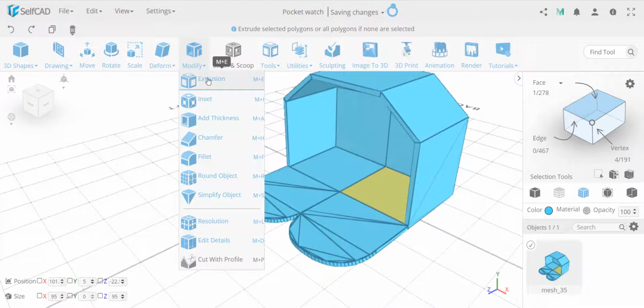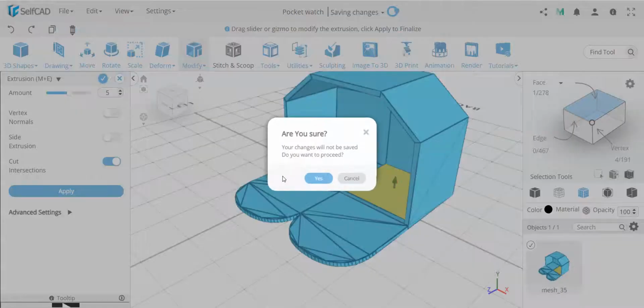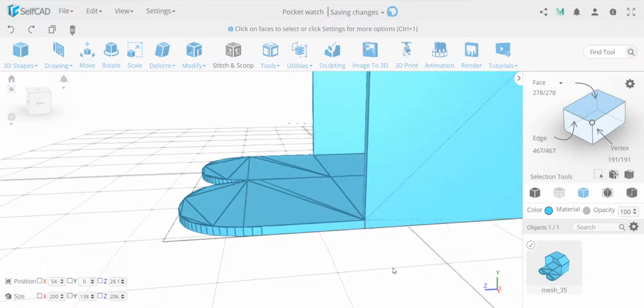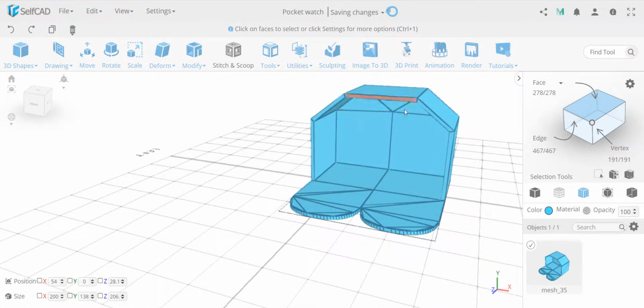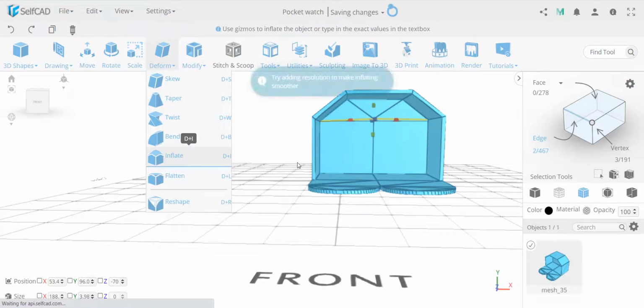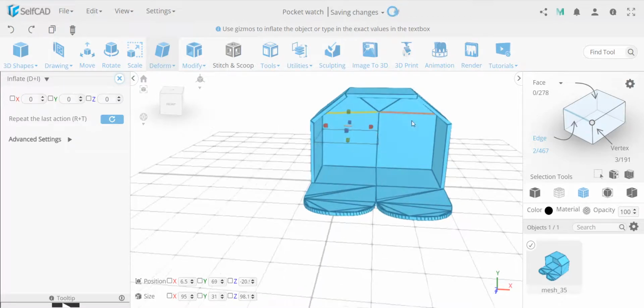You see the message is no longer showing that it's not manifold, because the object is now perfectly manifold because the extrusion created a cut. So in an example like this, you would be much better off first filling the inside, and then filling this. And by the way, this I didn't draw straight. Let's flatten this. I'll use the flatten tool to move them down.